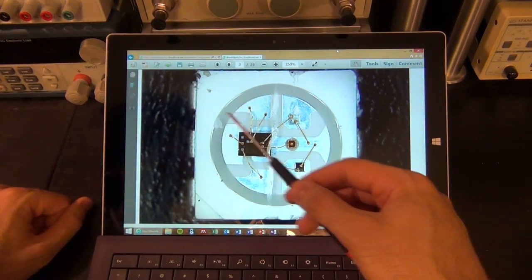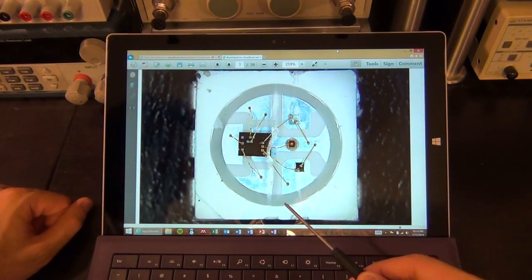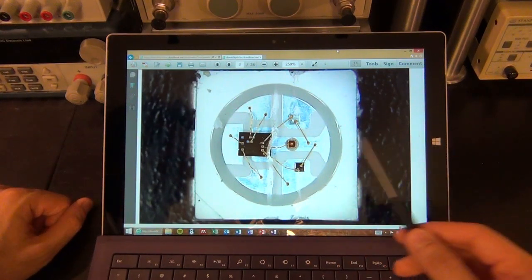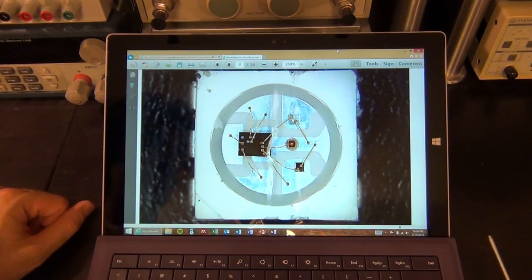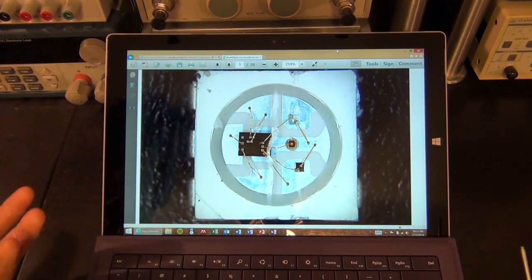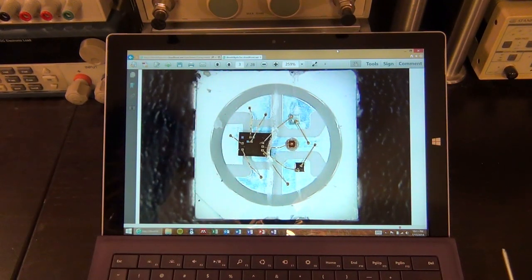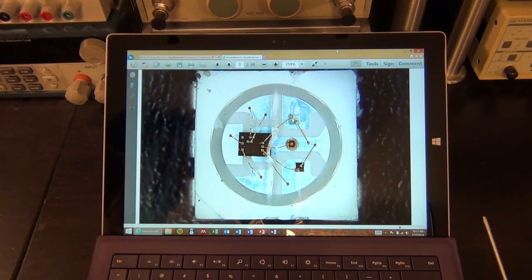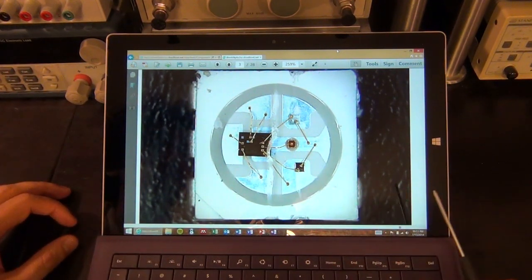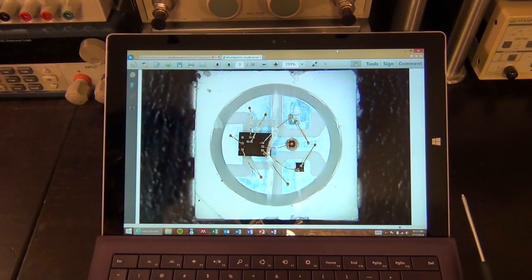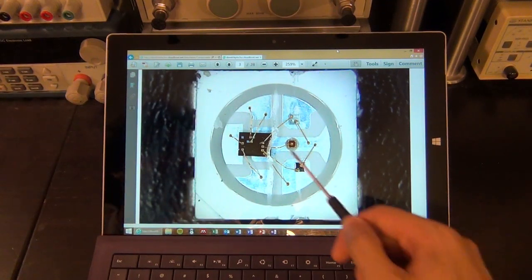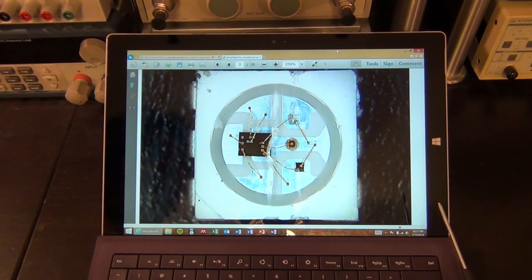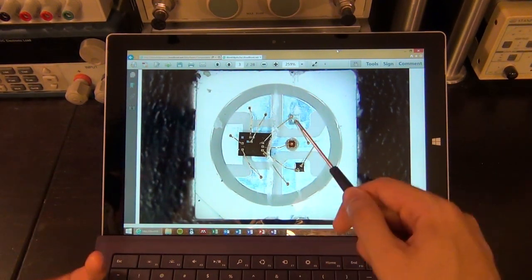At the same time, it buffers the data in and outputs it from data out, so that the next LED that's in the chain will receive the data. So how does it know when to light up, and how does each LED know when it's supposed to actually apply the PWM? There's a little trick. If the data input remains low for longer than a certain amount of time, then the IC will interpret that as the end of sequence, and whatever is in its buffer, it will apply as a PWM.